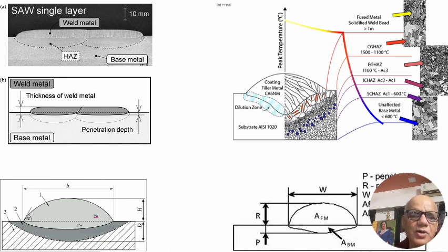Here our focus is a very shallow penetration, a wide bead, and a beautiful angle. I mean, the angle as it is shown here should not exceed 60 degrees. Ideally it should be between 45 to 60. It should have a very smooth profile, but if it goes beyond 60, it becomes too sharp for the subsequent run to get properly deposited.